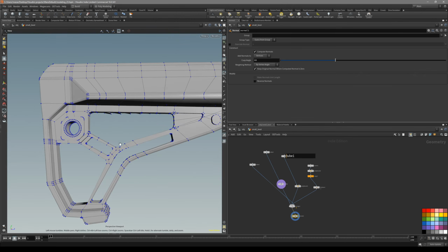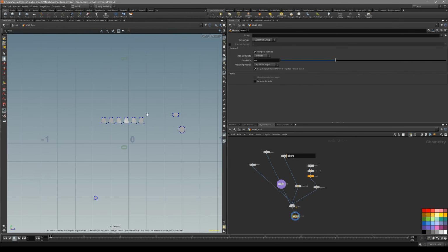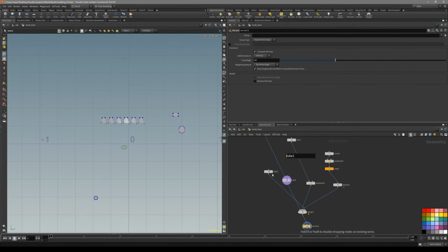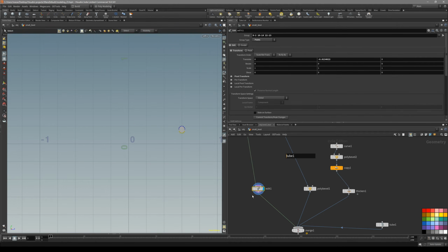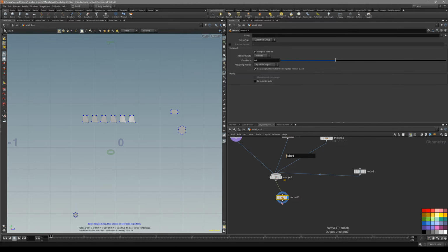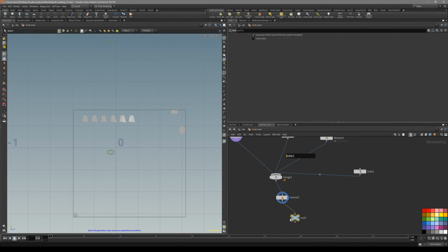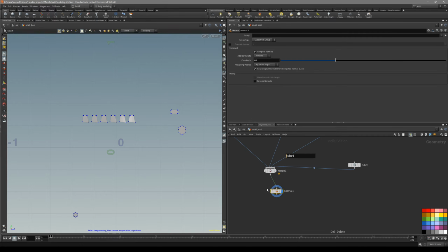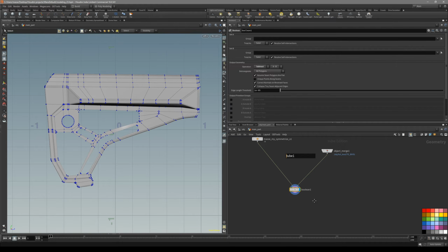Now I want to boolean them, but the thing is that although these are in different places, I also want to boolean them in different places. So the setup is very simple, just a couple of copy nodes and all that, bevels, edit, place them where they go, then merge, normal, and then we want to output. I want to null node it, and let's say actually we don't, let's do it without a null, and just reference this small bool in our bigger boolean.